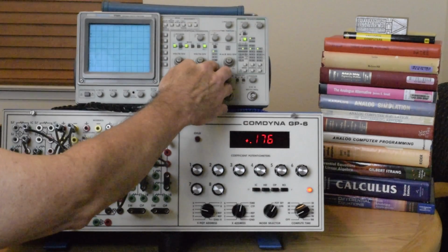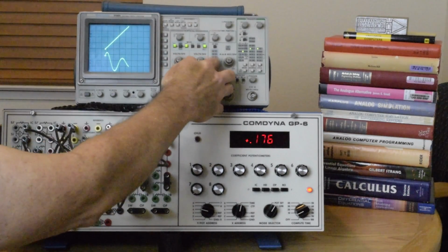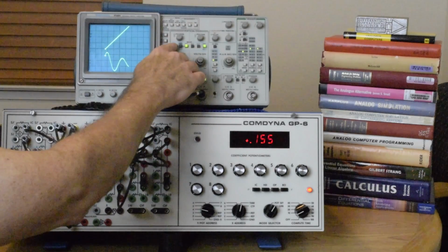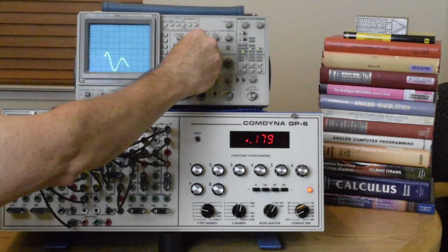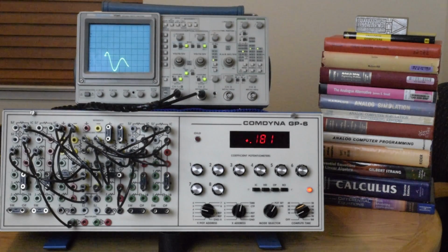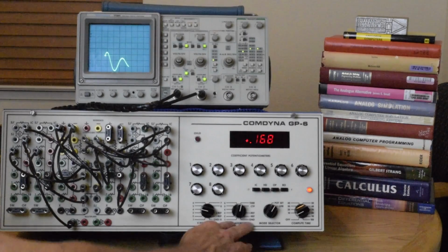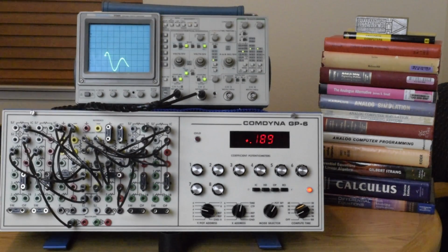And then when we actually set these to XY mode, we really have our solution there, but we don't want to look at channel 1, and because I rearranged the sensitivity of the channels, we'll have to recalibrate. So before I recalibrate, I'll switch over to the zoomed in image of the scope so you can see that a little more clearly. Basically I'll just be resetting these XY addresses to look at the ground plus reference and minus reference on both sides, and you'll see the calibration procedure.